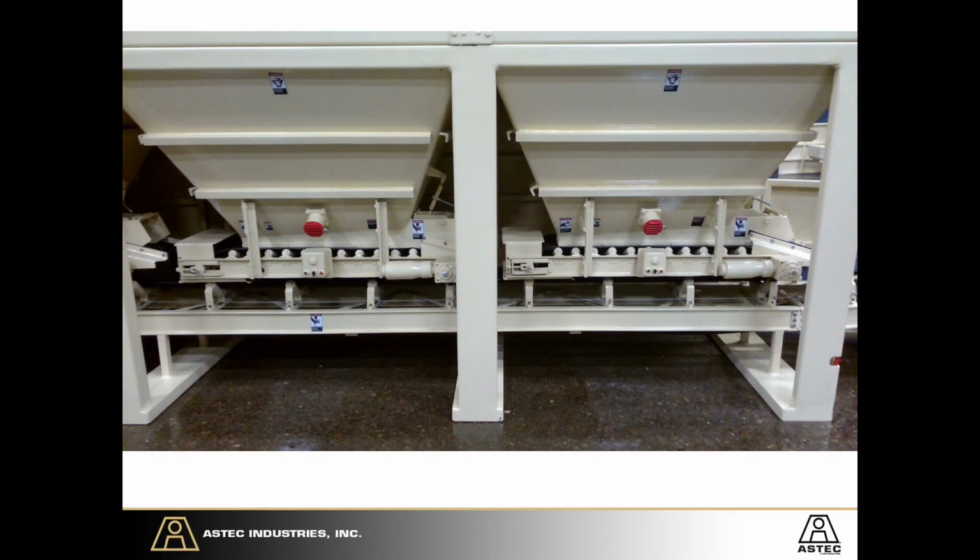Here's a side view of the bins. If you look at this bin, they are equipped with vibrators. These vibrators actually keep that material flowing. They can be designed a lot of different ways. Sometimes they can be connected directly to the bin. Sometimes they can have a dancing plate on the back. And sometimes you can use bin butlers or things like that to keep that material moving. But these vibrators can be controlled automatically or they can be controlled manually. One of the things that a lot of people do is when they see no flows, they hit these vibrators to keep the material flowing.